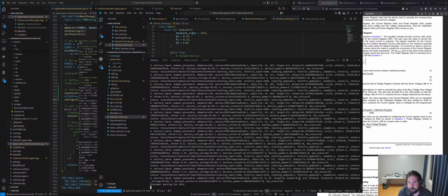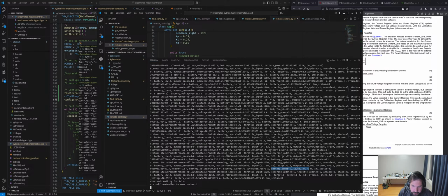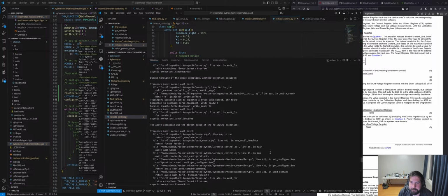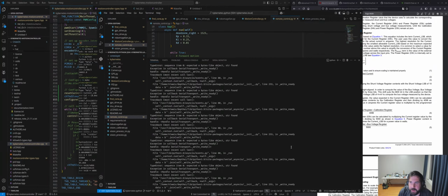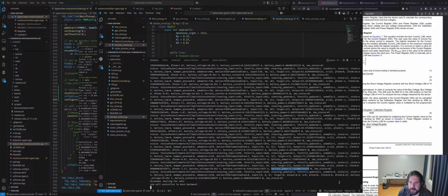We can see now it's at 5.7 watts instead of, there was a lot of output that it wrote out. Instead of, we were at what, 6.7, I think I said, right? 6.7 watts. So its idle power appears to be around a watt, which is not great, not terrible. And then its consumption goes up by another 3.6 to 4 watts running that object classifier and doing the video encode.